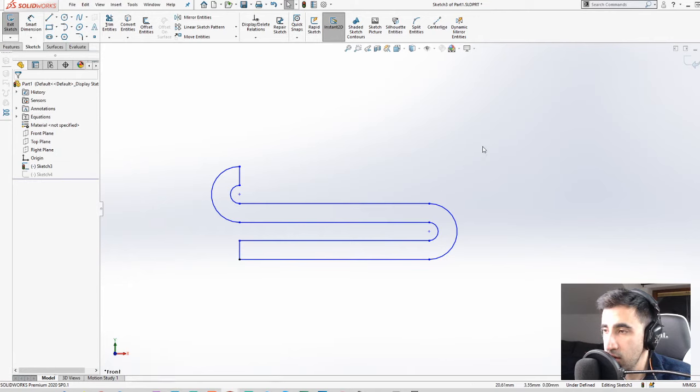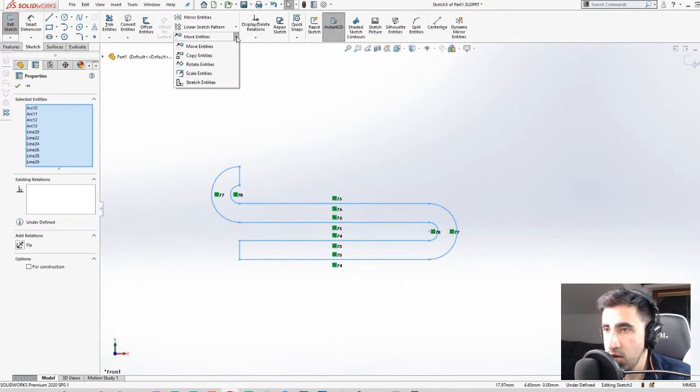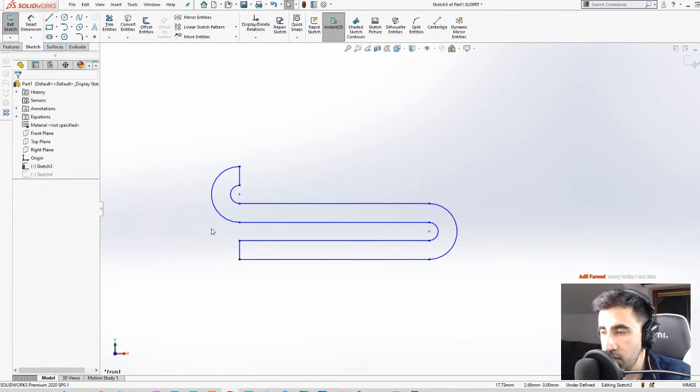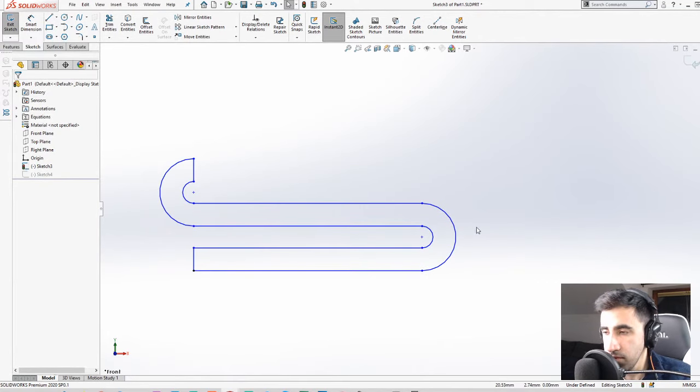If you don't know what I mean by that, I can easily show you by duplicating the sketch. Go in here, copy it, set it to from-to, and pick it from this point. So I have a copy of this sketch over here, and if I place this point on this point, you can see it continues itself onward. If I place it here, you have a discontinuity over here or anywhere else. These 2 points, therefore, have to be in a vertical relationship with each other.